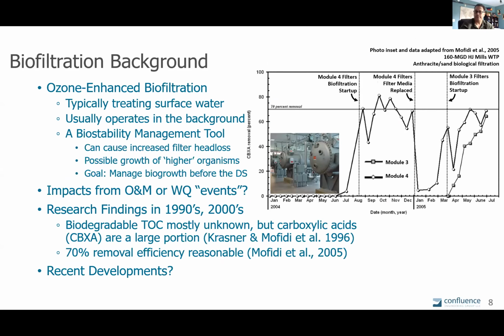Some of the impetus of the project is how do we know what operating events, what water quality events impact the filter and its efficiency, which led to the work here. And we tried to base this establishment of this monitoring program on a lot of research and work that I've been involved in the past. You see a graph here showing some of the results from past publications, where a lot of facilities now use different parameters, such as what's shown here, carboxylic acids, some low molecular weight compounds that are biodegradable and can be monitored through an IC chemistry method.